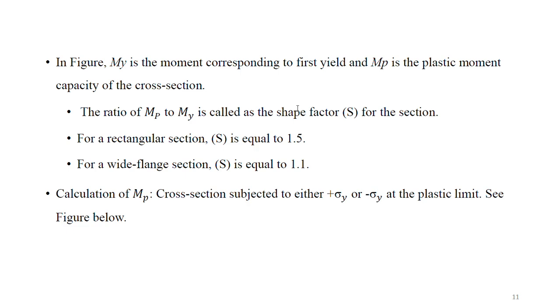Okay, for the calculation of plastic moment MP, we take the cross section which is subjected to the maximum tensile stress and maximum compressive stress, up to their limits. The section is going to fail in compression or the section is going to fail in tension. Both conditions we take.